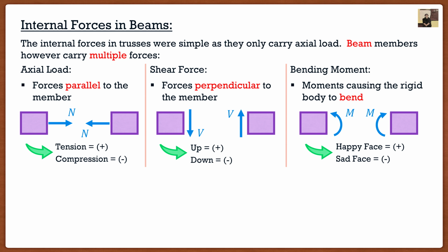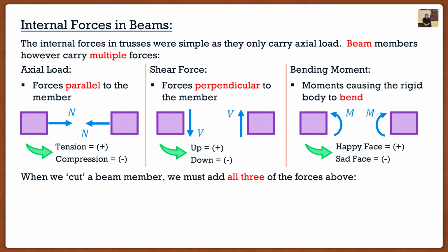Those are the three internal forces in beams, all right? So it's actually not too bad. What happens when we want to determine these internal forces is going to be the exact same procedure as before, where we simply cut our beam, but instead of just having an axial load like we did in trusses, we actually have to add all three of these forces that we have above.